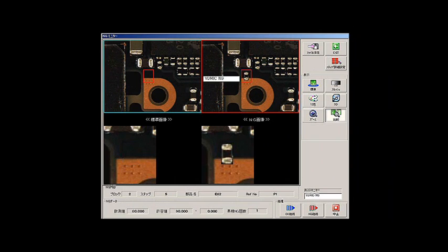Here is an actual inspection image taken from an ordinary inspection unit. It extracts any discrepancy on every board regardless of conditions. So the inspection unit mistakenly detects many kinds of situations as errors due to light conditions or variations among components from different manufacturers. To eliminate this problem, VADMIC was given a learning function to meticulously reject all false information.